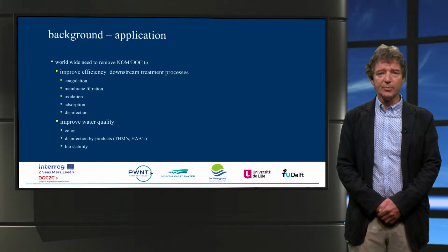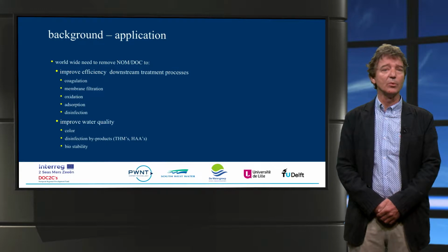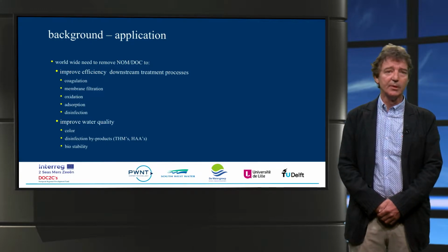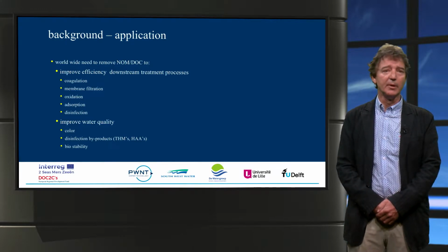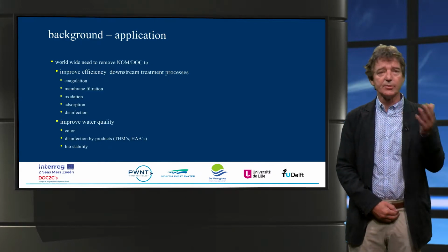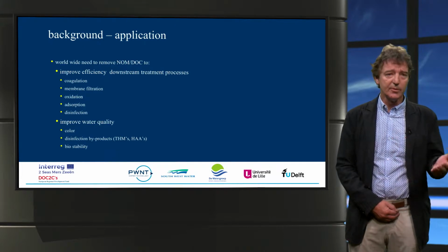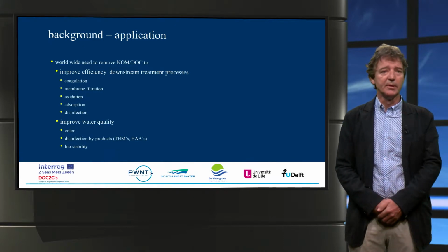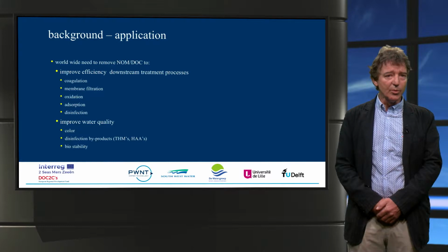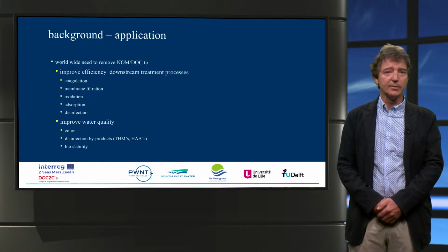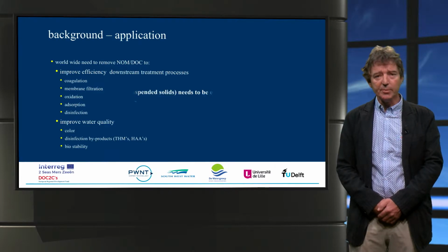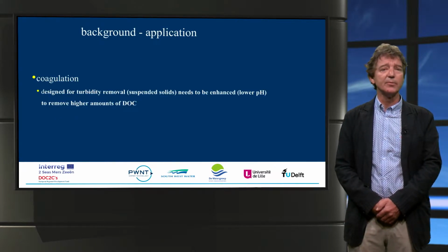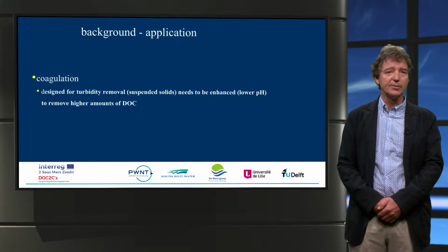The importance of NOM removal in drinking water production is obvious. We see that there is a worldwide need to further reduce NOM and DOC levels in order to improve the efficiency of downstream processes such as coagulation, advanced oxidation and disinfection, and to improve water quality in terms of color, disinfection byproducts and biostability. In principle, there are two technically and economically feasible methods to achieve this goal.